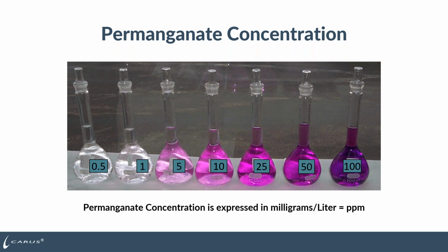The other thing, besides the coloration of permanganate being the same, regardless whether it's potassium or sodium permanganate, is that all the reactions are the same. So all the chemistry, if you're removing iron and manganese, taste and odor compounds, or organics that cause disinfection byproducts, sodium and potassium permanganate is going to react the same way with all those constituents, and you're going to have the same oxidation reactions. So there's no difference.